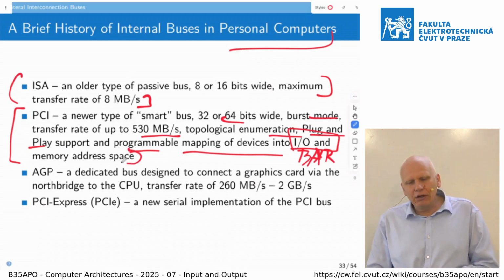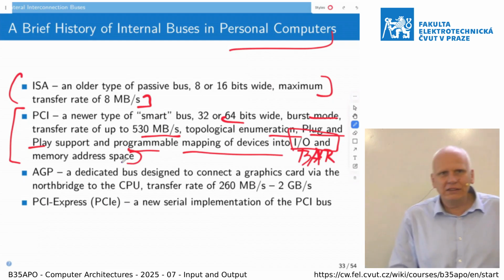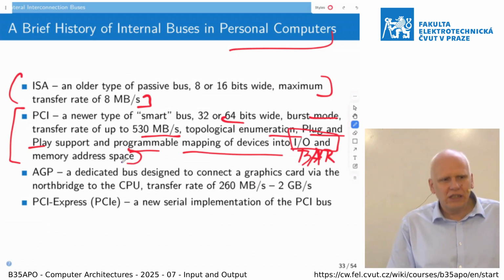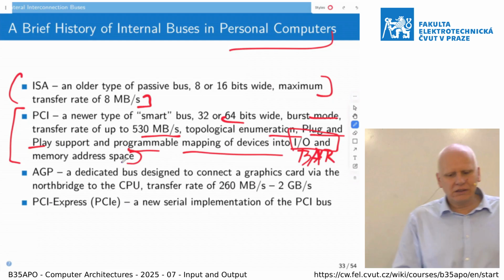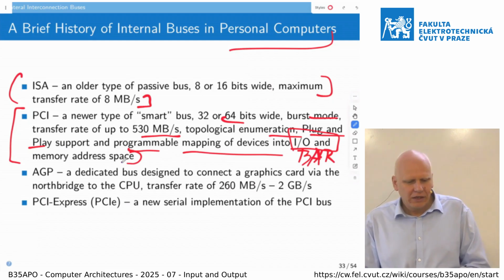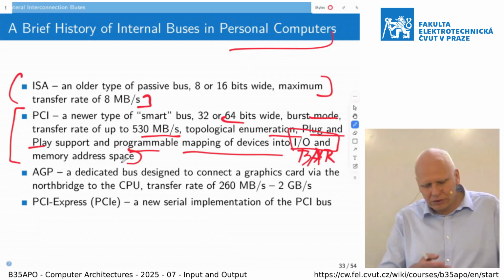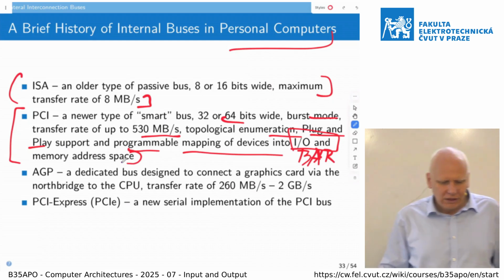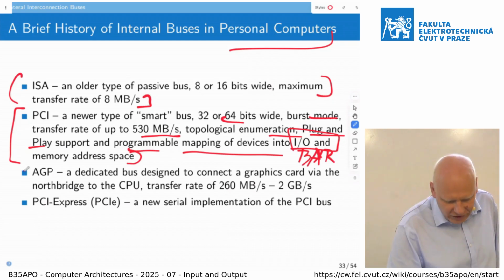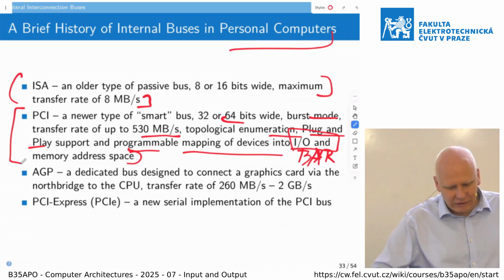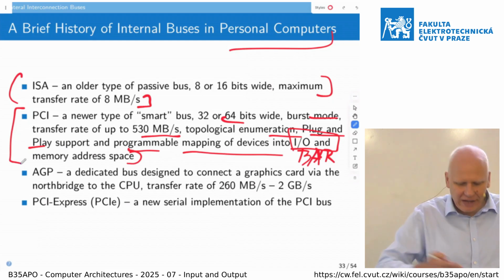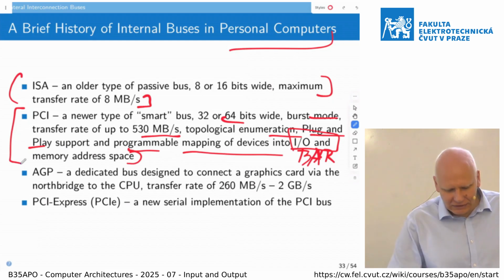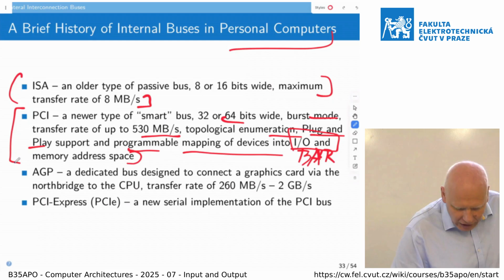It even allows the peripherals to initiate the communication back, to access the memory directly and store the packet to the memory without the CPU. The CPU sets up the peripheral where the data should be stored, but doesn't need to assist with individual bytes.